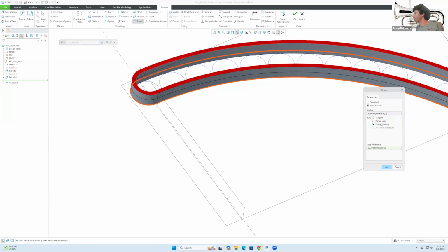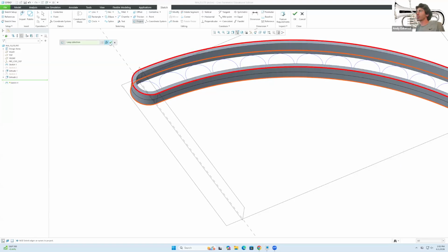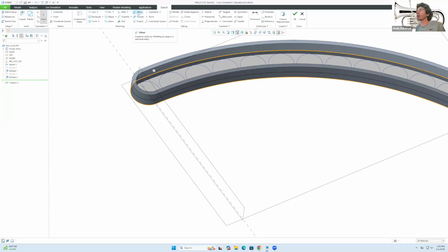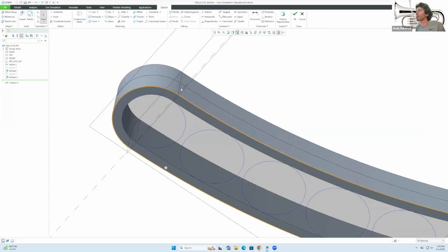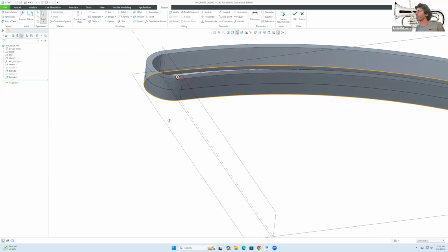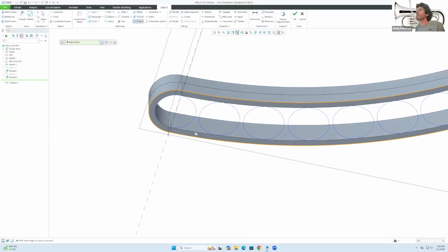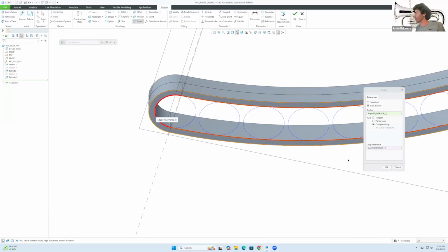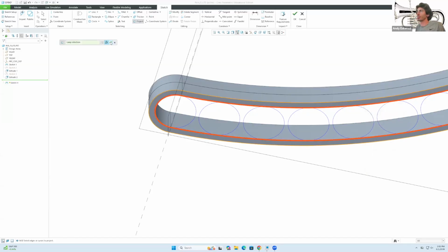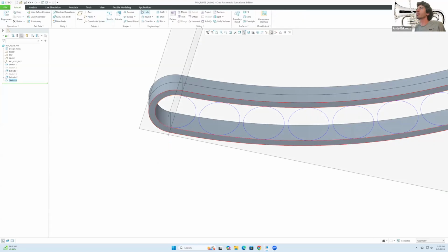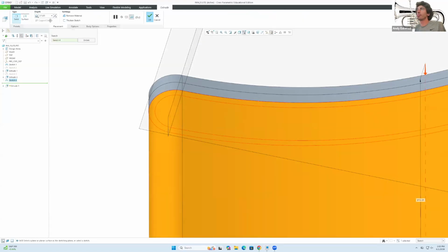Let's do a complete loop. Good. And now let's do another projection. Where are you? Excellent. So now we got that face in there. Okay. Extrusion by 10.